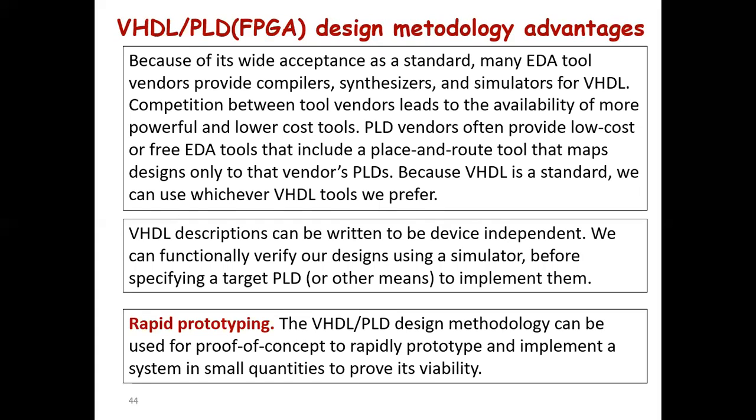We can functionally verify our design using a simulator before specifying a target PLD to implement it. Rapid prototyping: the PLD design methodology can be used for proof of concept, to rapidly prototype and implement a system in small quantities to prove its viability.